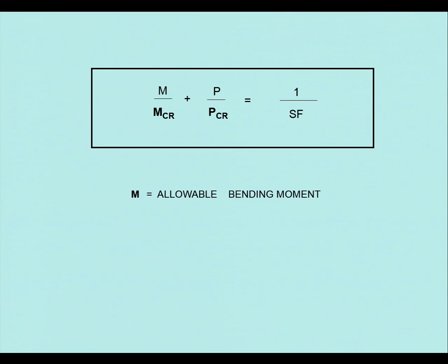So I've got a critical pressure which will collapse on its own without being bent. I've got a critical bending moment which will bend without a pressure, but I've got an actual pressure P from the water depth, so I now need to know what the allowable bending is to avoid collapse, and I put a safety factor of 1.5, 2.